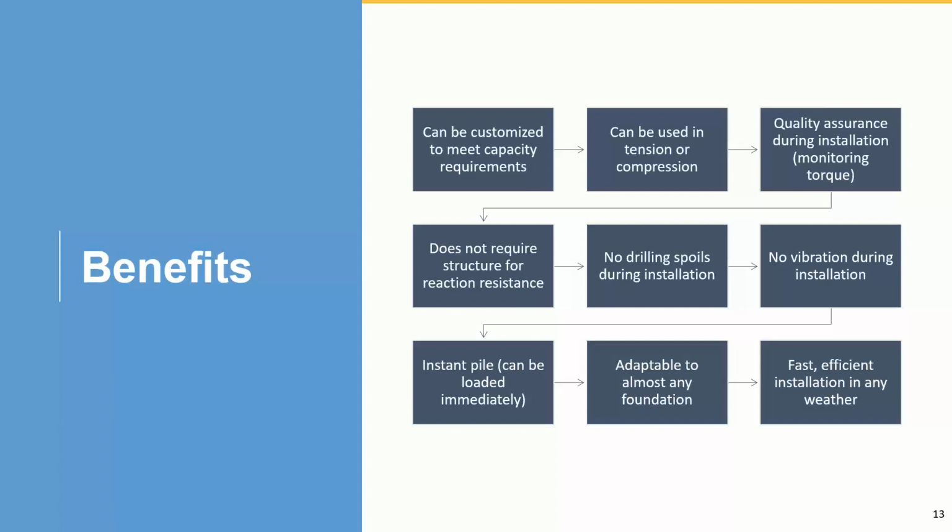So when you install it and get the final installation torque required, you're sure that this pile is going to meet the design capacity. So it can be used as quality assurance for installing helical piles.